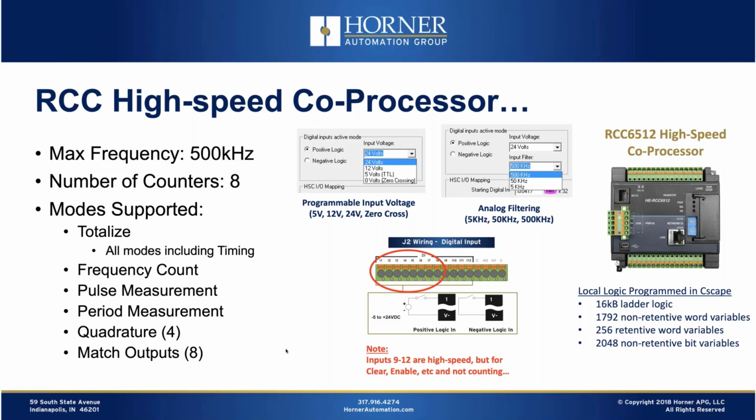So again, filtering is very important when you have a high-speed counter that's got high frequency support. And in the case of this product, we do the filtering in an analog domain, and it does a really good job of it.